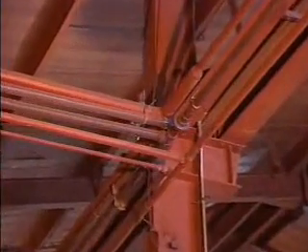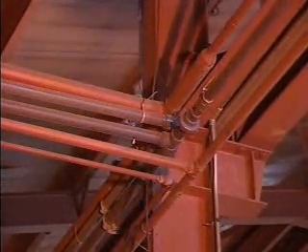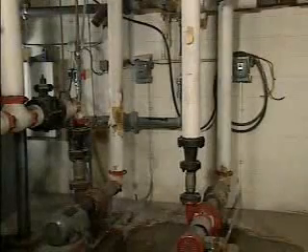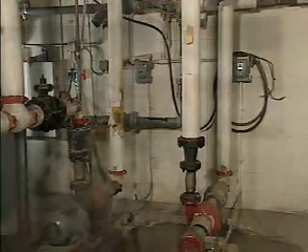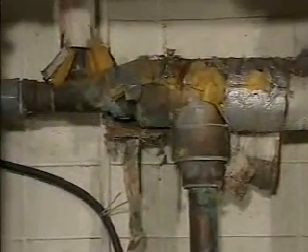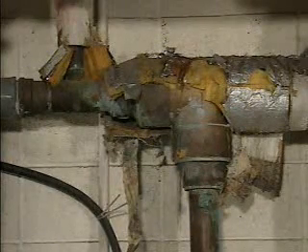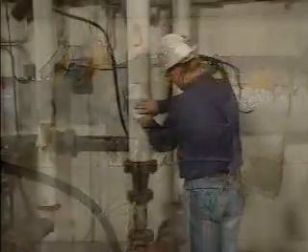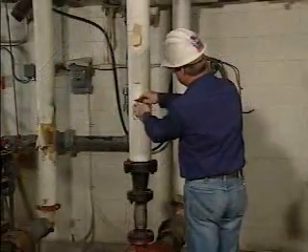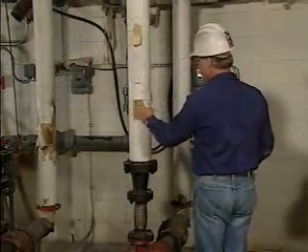Providing additional support or protection to the pipe may be necessary to prevent additional wear. Finally, if a pipe is insulated or has a protective covering, these should be inspected as well. Look for soft spots, discoloration, or rust, which indicate that damage from moisture has affected the insulation. Worn or damaged insulation should be removed and replaced.